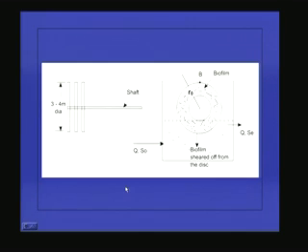Now we will go into the details of the process. If you take a shaft, it is something like that, and you will have many discs attached to the shaft with some spacing between the discs. A series of discs will be arranged like that. Usually the disc diameter varies from 3 to 4 meters, depending upon the wastewater flow rate and the capacity we need to design. Or if you take the other view, we will get it like this.